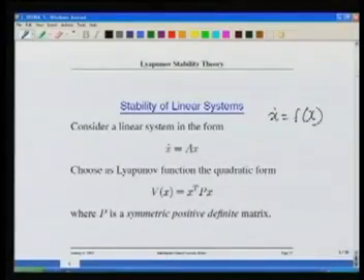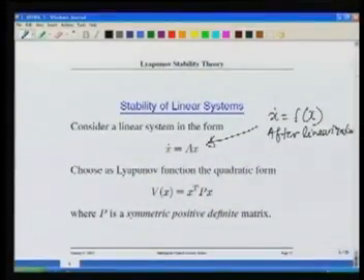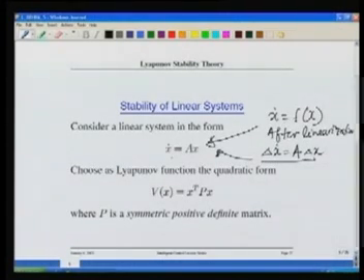Now, we go to the next further discussion. Our actual system is x dot equal to f(x), and if you linearize it, after linearization we write x dot equal to A x. In linearized dynamics we just make our symbols very simple. The linearized system is actually delta x dot equal to A delta x, but for convenience we represent this equation as x dot equal to A x. This is our original nonlinear system, and this is the linearized system.